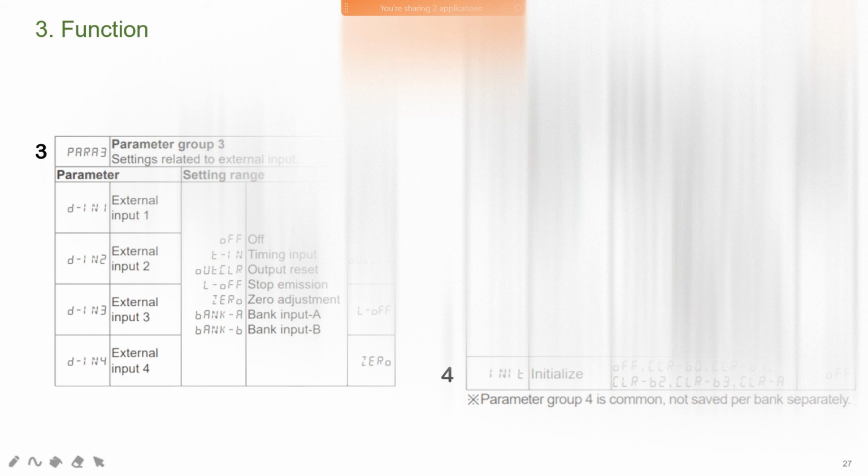Okay, this one is display direction, you can flip the display also. This one is for bank recipe setting. It has a 4 bank setting, and then save bank mode. Okay, if nothing is pressed on the key of the amplifier, the light will turn off. This one is a saving mode. And also have a lock mode. Lock mode, you prevent someone from playing with the auto zero function.